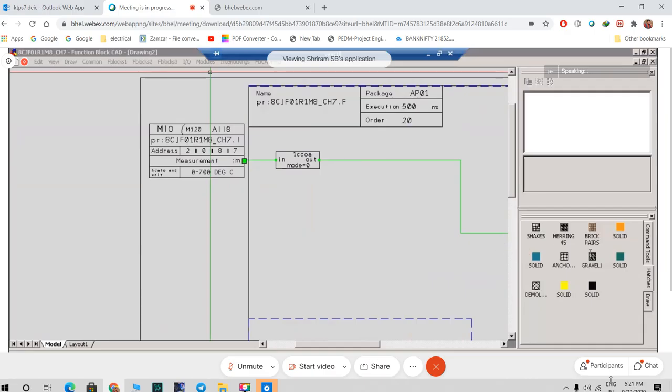What will happen if we download the main loop and child loop for a PID online? You can download a main loop and a child loop of a PID. The only thing is you have to note that it will reset to its original state because it is a controller. Suppose your control valve is at 50% and then you download. Basically, the initial value given in the PID is 0, so your control valve will first go close to 0 and then come back. It will not be a smooth transfer when you give an online download. So whenever you are downloading these loops, you should be careful so that your process is not affected. Usually, if you have changed only some values, you can give a download update instead of a download replace, so that only that particular value is changed. And whenever you give a download delete or download replace, you had better do it in a shutdown condition so that your process is not disturbed.